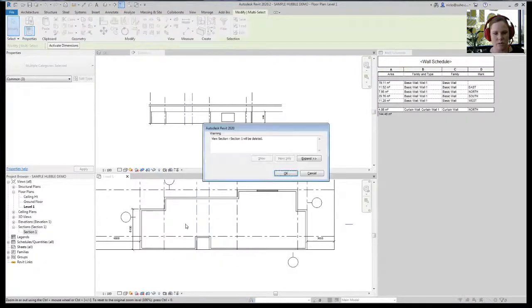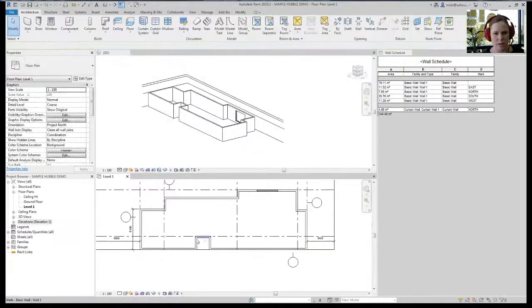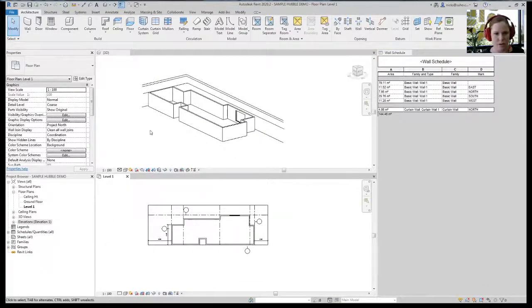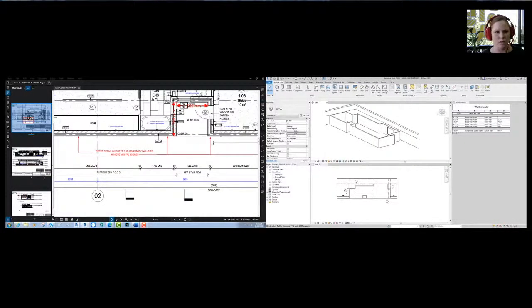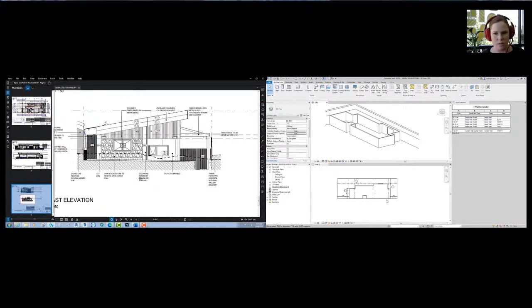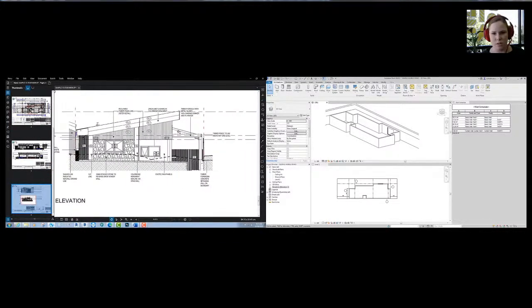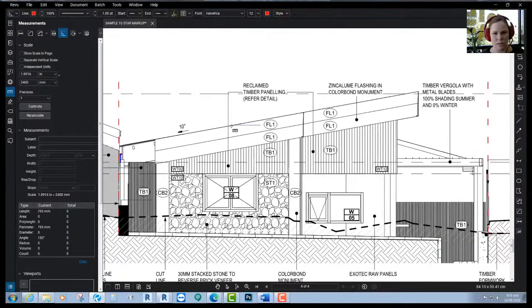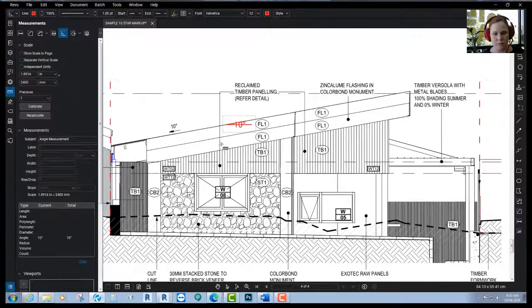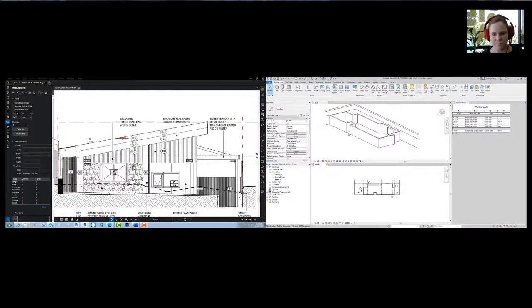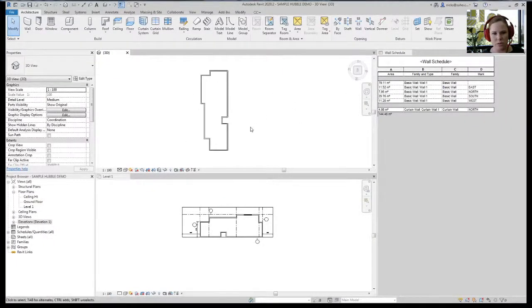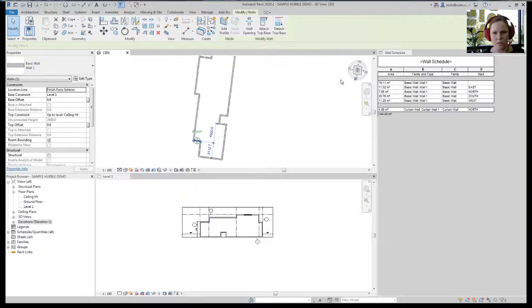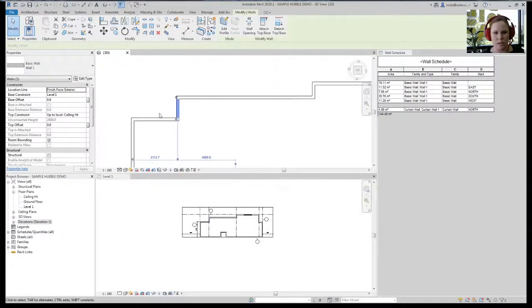Okay, good. So you're getting a few inside tips here in terms of how quickly we can do a performance model at SUHO using this software, and why we can possibly give a builder with the client a much easier estimation process, because there's a lot of data that's already in there. Expectations are also set in terms of the performance of the building, and then we can get a much better dialogue. Okay, so I've just measured the pitch of the roof. Now in Revit I wanted to make sure that I'm calculating the wall areas that are also going up to the roof. So I'm going to draw the roof on, and then we're going to attach these walls to the roof. Let me just make sure that we have them all allocated.